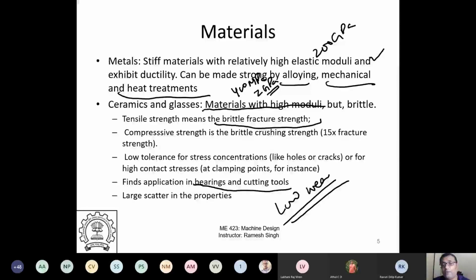If you go even higher, you will have to go to air bearings and even magnetic bearings, because you don't want any wear, so it has to be suspended. But between your ball bearings, the balls will be made of ceramic, so you can make very high speed mechanical bearings using these ceramics.